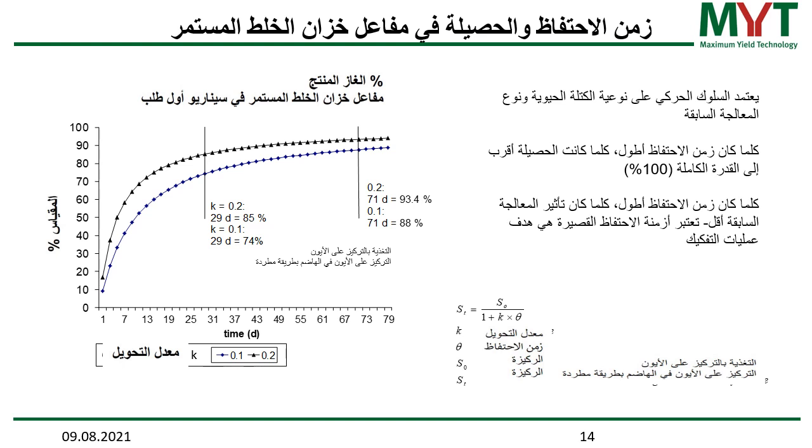As you can see, at certain retention times, I have put down the numbers here for two different points, 29 days retention time and 71 days retention time. You can see that the difference between these two systems is changing over the course of time. At 29 days retention time, the difference is from 74% to 85%. So it's essentially 11% more gas here.